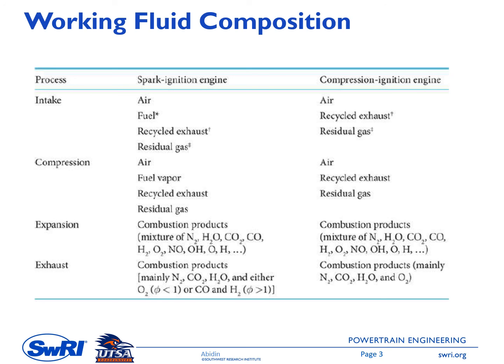You can see here for the spark ignition engine during the intake stroke, we have a working fluid consisting of air, and then it might include fuel if we have PFI, port fuel injection, or it might only contain air, plus recycled exhaust. So in the new engine technology, exhaust gas is recycled back to the engine for better NOx emission. We will look at this in more detail in chapter 11.